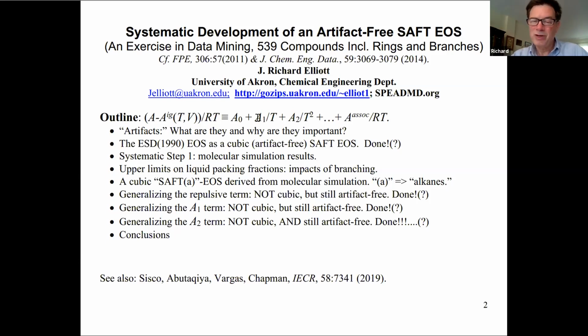But then we lose accuracy with respect to the first order perturbation contribution in this Taylor series expansion. Well, could we generalize this first order term? Because that's a very, very important term to get your vapor pressures right and all your thermodynamic properties right. So we need to be able to generalize that. Turns out that's easy to do, and there's not a problem.